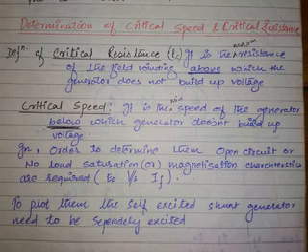In spite of this, still the voltage is not getting built up when you start the generator. It may be due to improper brush contact.